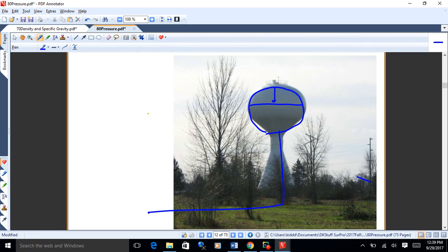What they figure out is, okay, we want a certain range of pressure for our system. Normal water pressures might go from 20 to maybe 60 psi, something like that. So they'll figure out for this surrounding area that this tank feeds, let's say this tank goes from 120 to 80. What's the range of pressure they get out of that tank? Instead of the straight simple 100 that I gave you, what if it varies from 80 feet when it's drained down low to 120 feet? What's the range of pressure you'll get around that tank?